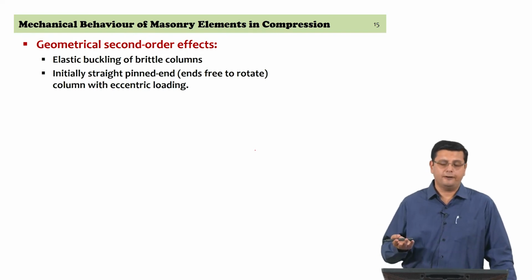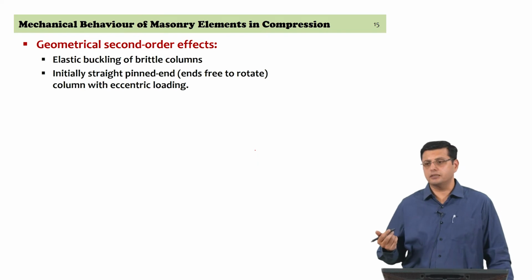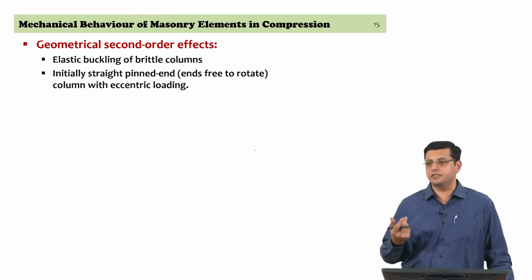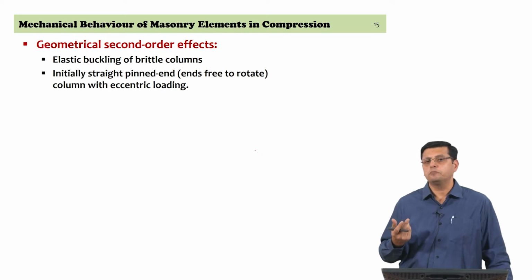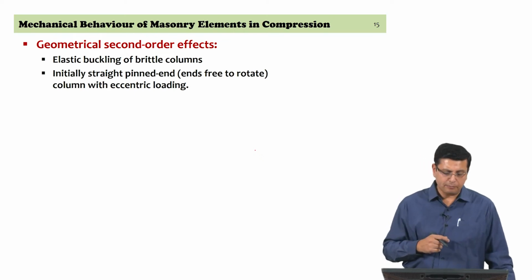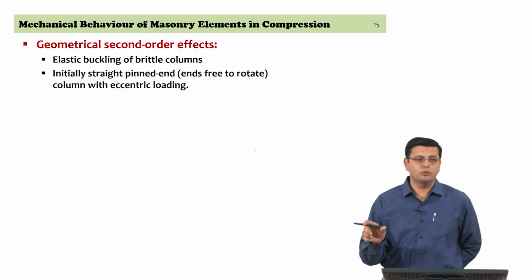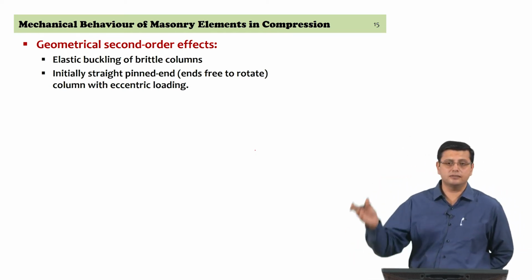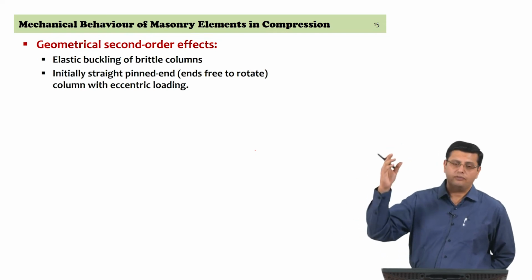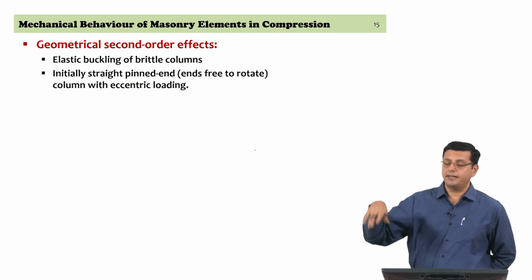That is, you might ask me, when you construct a masonry wall, how is that you get pin conditions at the ends of the wall. But typically what happens is, you have a different material on which the wall is constructed. It is not brickwork that is going to continue for the entire length of the building, entire height of the building.